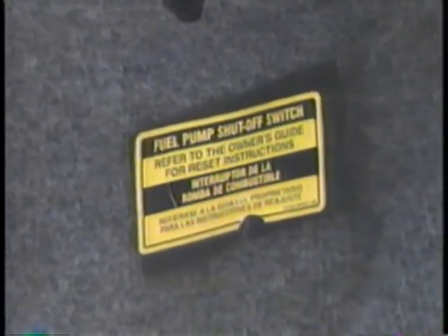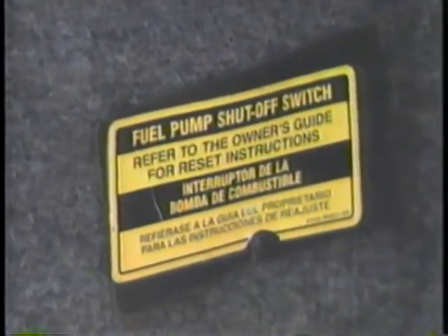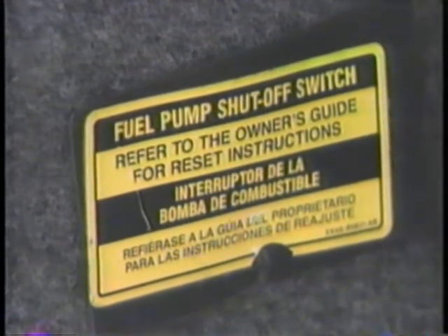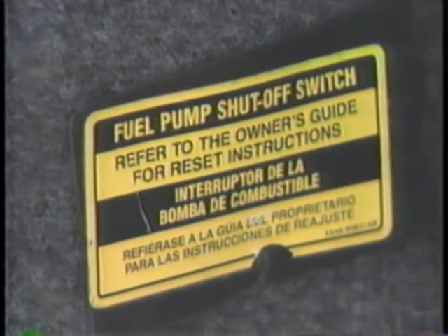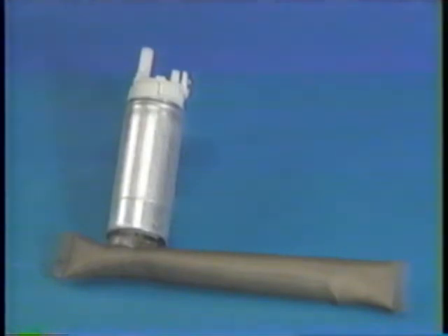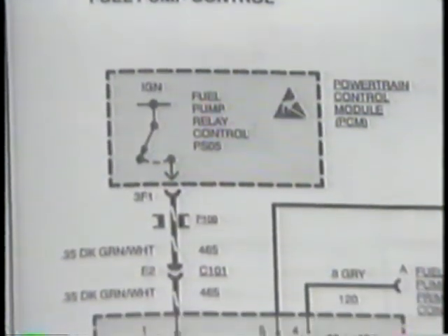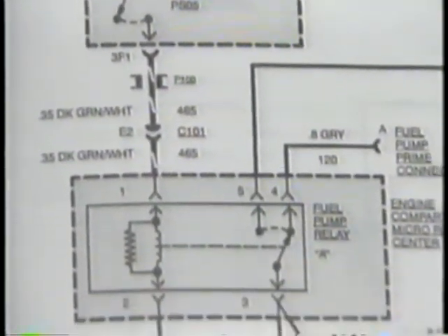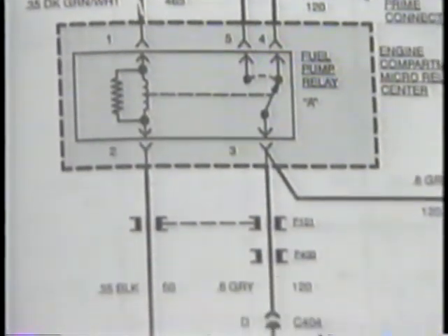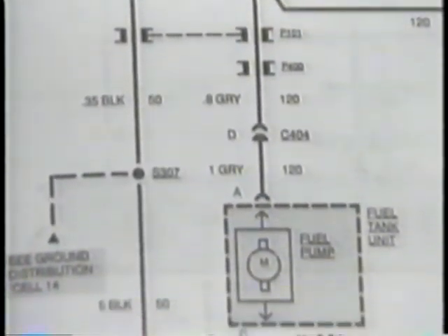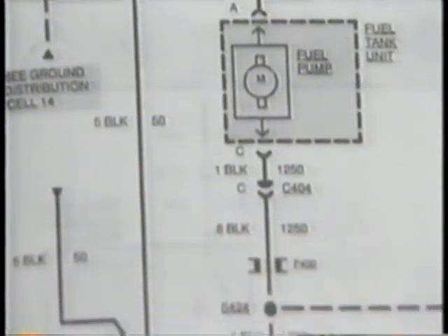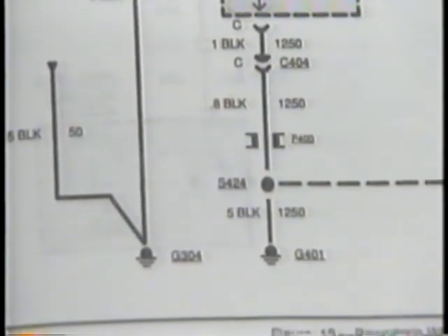Other systems are also designed with safety in mind. For example, vehicles with electric fuel pumps often have an inertia switch designed to open the circuit in the event of a vehicle crash. The pump itself often contains a check valve that stops the flow of fuel in the event of a rollover. Other vehicles equipped with electric pumps are high side or positively operated electrically. This design ensures that an electrical short to ground in the event of an accident will stop power flow to the pump.